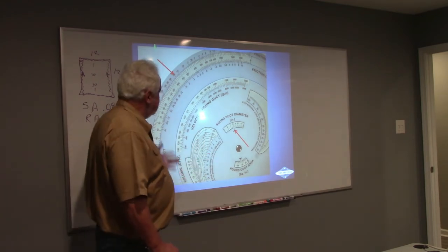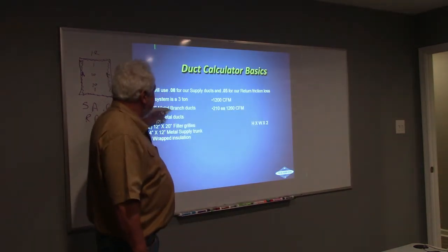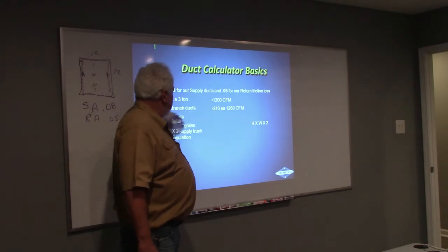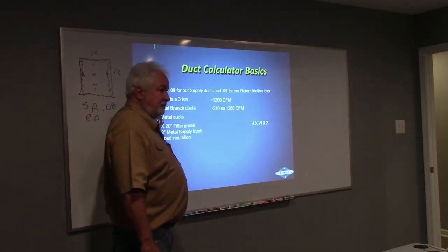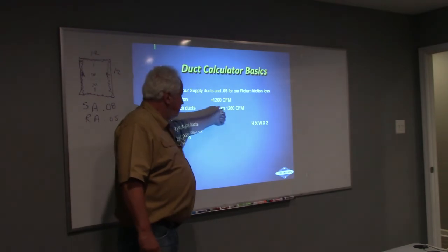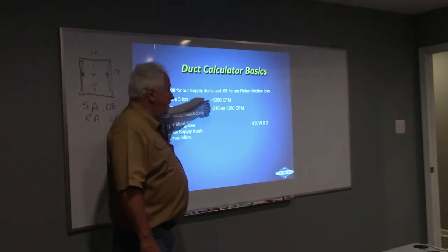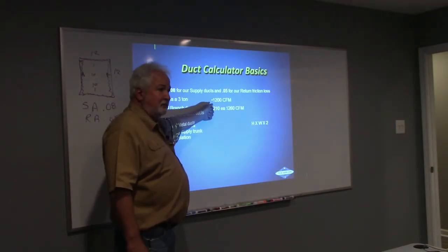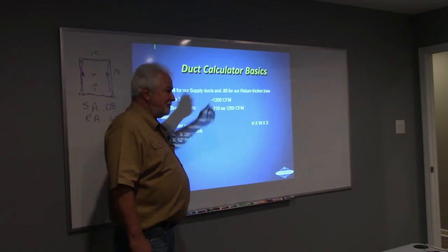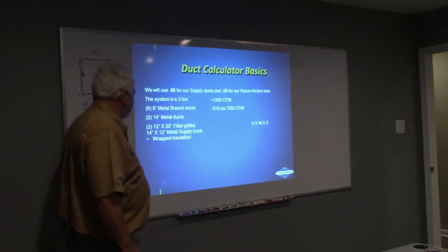All right. So I said it was going to be about 210. If I have 6 of those, 6 times 210 is 1260. Is that going to move my 1200 CFM that I need to move? Yes. Yes, okay, good. I thought I heard a no somewhere, all right.